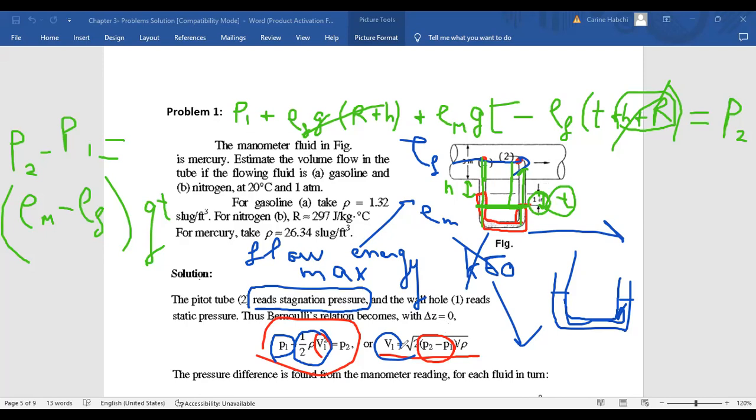When you take fluid dynamics, you will see that this device, which is called a pitot tube, is used to measure velocities. What is the idea of this equipment? The idea is I can force the fluid to have a velocity of 0. So I can link the velocity V1 to the pressure variation because of Bernoulli.